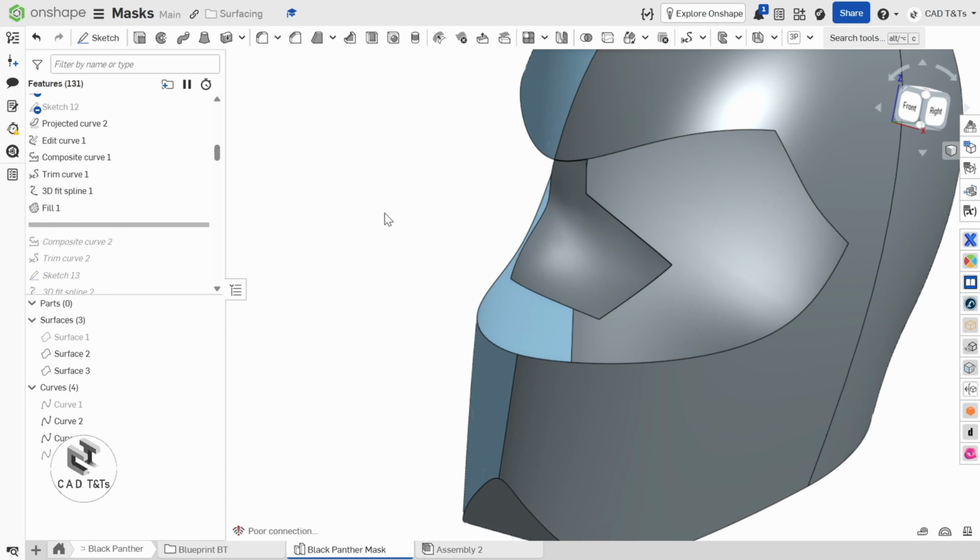But if your boundaries are open, you can use the extrude, you can even use the revolve, you can use sweep, and you can use loft. Loft can be used in open boundaries and with closed boundaries. And sometimes the result from loft is not the same as fill, but it's often close. I mean about the curvature, about the quality of the surface you want.